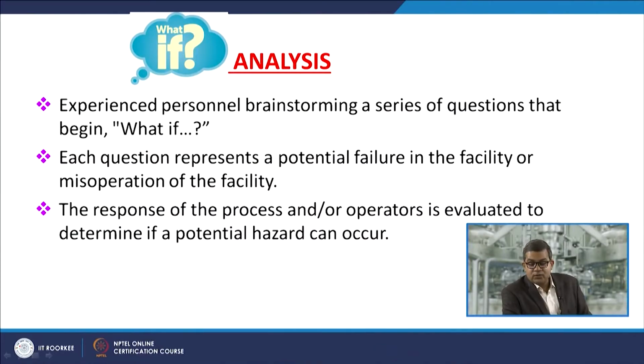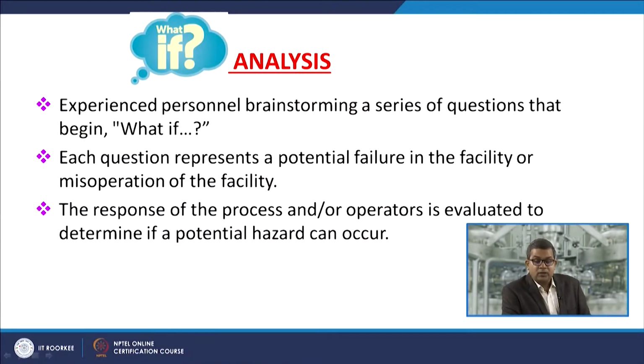Now certain experienced persons carry out what-if analysis. The experienced persons brainstorm a series of questions that begin with what if. Suppose it happens, then what if? Each question represents a potential failure in the facility or misoperation of the facility. The response of the process and/or operator is evaluated to determine if a potential hazard can occur. So you need to find out the what-if answer.